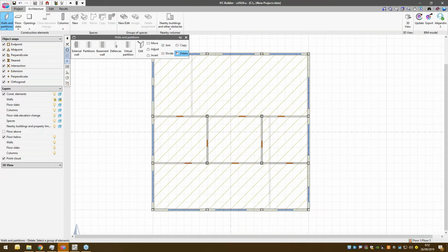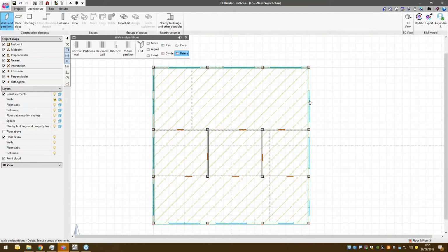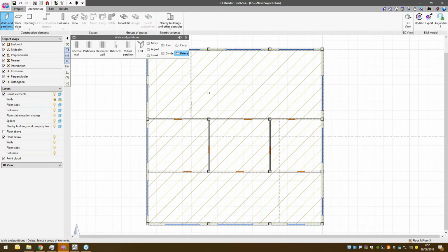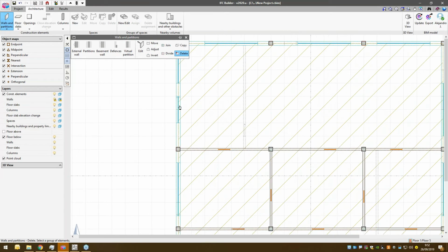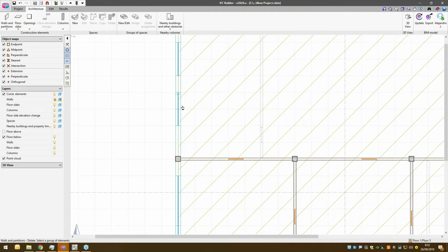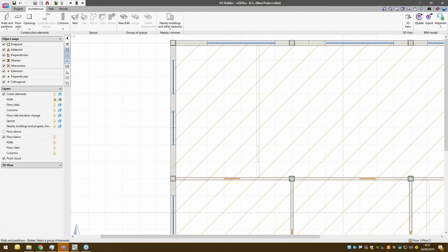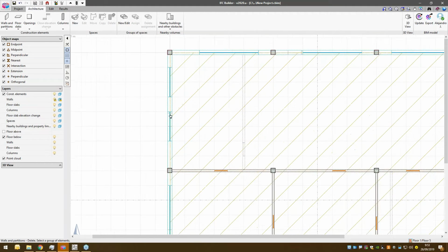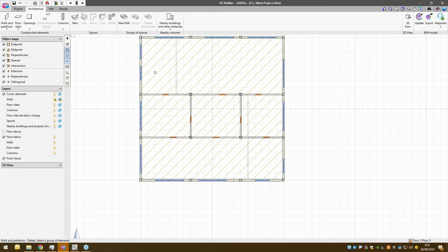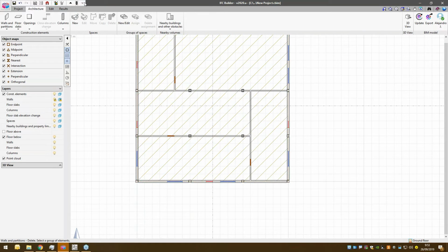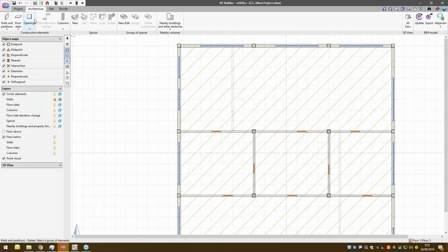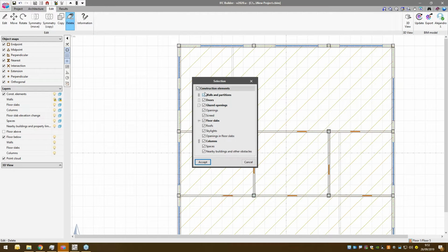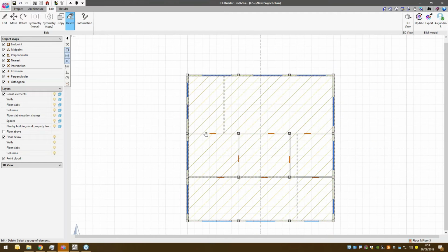this model can be exported afterwards for conducting a thermal and energy calculation and an energy certification. So for now, because we are using Energy Plus as calculation software, right now we are obligated to define glazed surfaces as a series of windows. That means that if you want to make a surface a glazed surface, you have to do it like this. Let me for a second edit, delete, and delete only glazed.